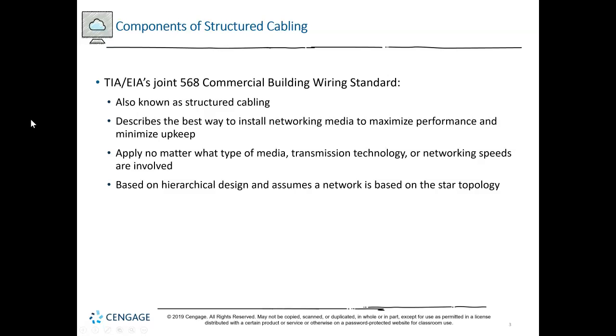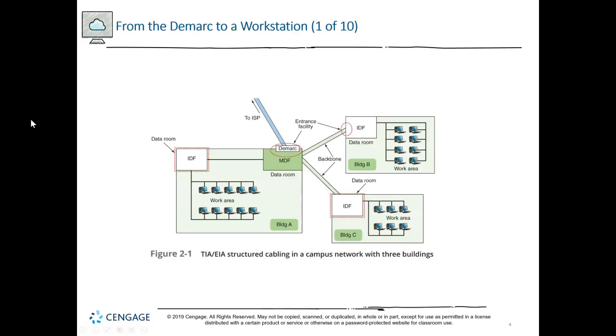So 568 is a number you're going to see a lot. You're going to see 568 because that describes structured cabling. So if I say, hey, did you cable those with 568A or B? Oh, well, there's some terminology there. So a couple of things. They've got some best practices, so you can go out and find out how often do I need to staple a cable to a wall, or how does it need to be supported, or what's maximum cable length, and all those different kinds of things. They give us some guidance on how this should be done.